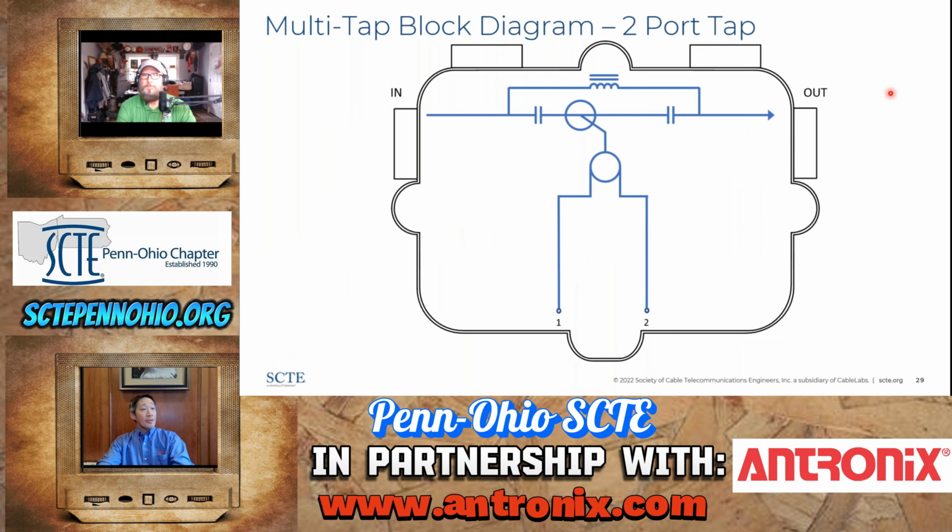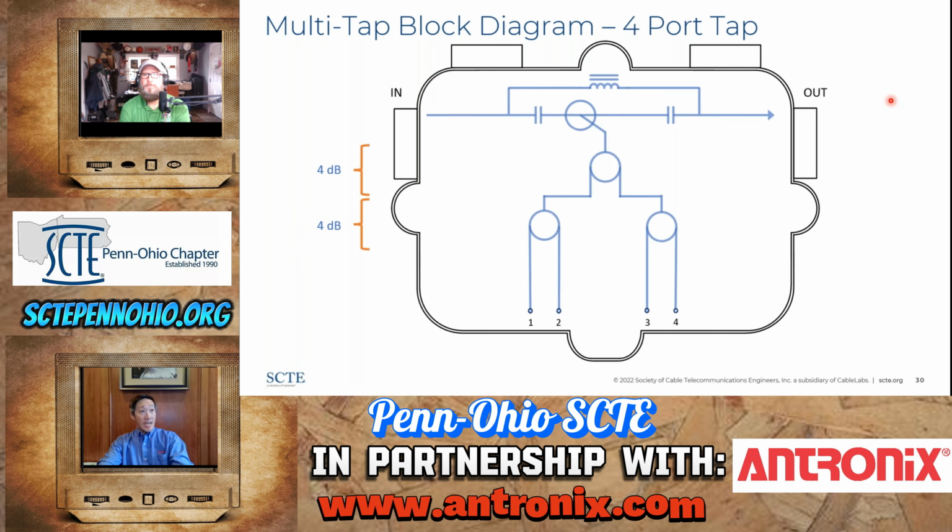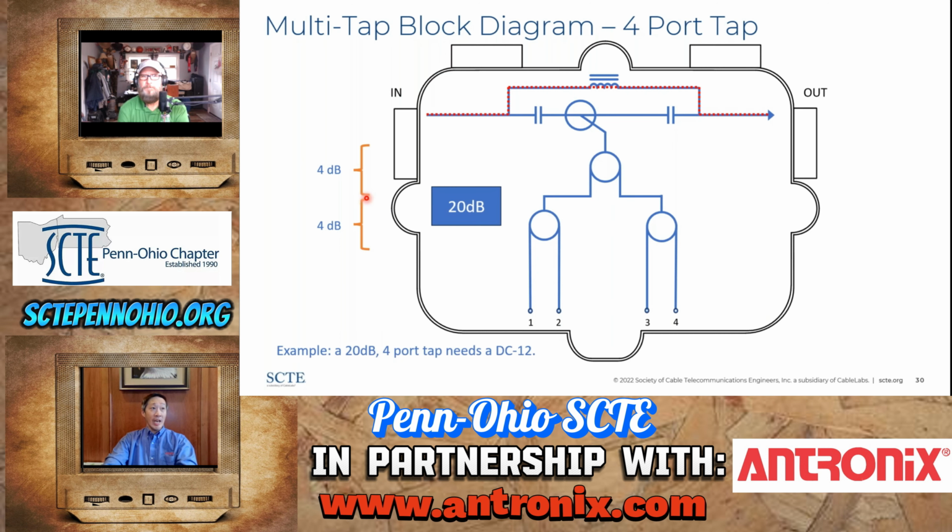So that's a simple block diagram for a 2-port tap, but as you go to a 4-port tap, it's just adding an extra set of two-way splitters to create a 4-port tap. Note that you have an extra 4 dB of loss going down here. So each set of splitters is 4 dB, so there's 8 dB of splitter loss going down this tap port. So you would need to select the correct directional coupler value to get the right tap value as you go from a 2, 4, and 8-port tap as well.